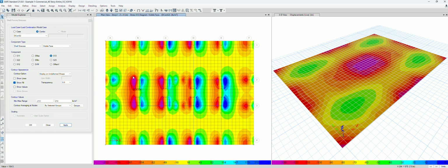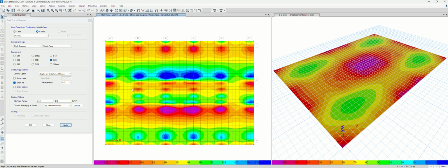But even if the average shear stress is exceeded over the concrete shear strength, we may have to consider increasing the thickness or adding local shear reinforcement. Same thing as 2, you need to show, right? But obviously you see the higher shear stress, which just makes sense. Our wind effect blowing in the y direction is more wind load, because the trajectory width x versus y is different, so wind load blowing in the y direction is much bigger.